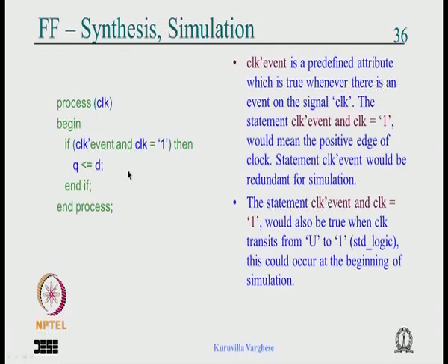That means there is no problem in real hardware, it does not happen in real life, but in simulation this can happen, and that can be problematic. Suppose you have a counter which is counting something, and if this happens it will start counting at the beginning only. There is a miscount at the beginning, but in real life the count will be 1 less. So you should be very careful.